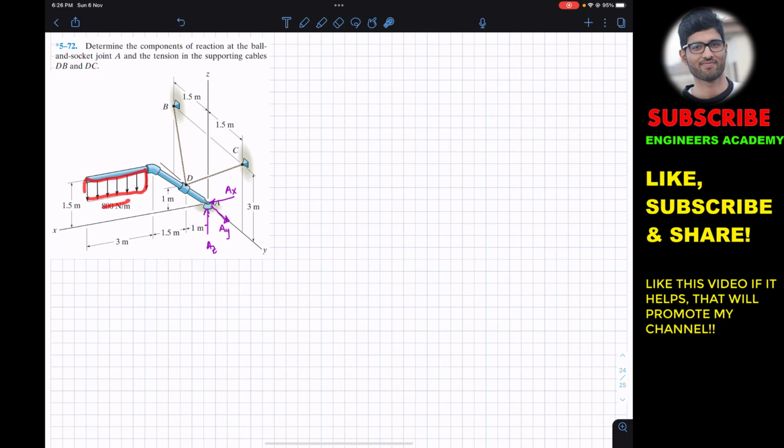So that gives us 2400, and that 2400 resultant will be acting at the center of this distributed load area, somewhere here, at a distance of 3 divided by 2, that is 1.5 meters from this particular end.